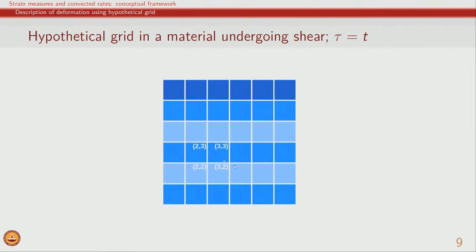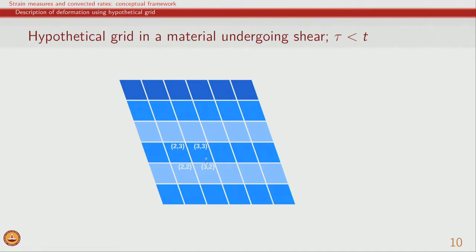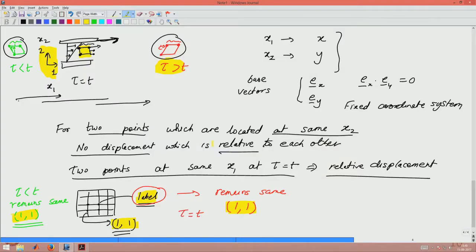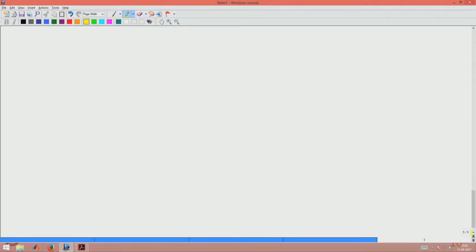and so therefore, these numbers that I have written here are in fact the convected coordinates, because the material particle is now labeled using these coordinates, and these coordinates are labels of a material particle. The material particle can change its position, but its label remains fixed, and since our coordinate is same as the label, the convected coordinates do not change. So, this is a unique way of following the material deformation, and this is somewhat counterintuitive to the cylindrical or rectangular or spherical coordinate systems that we usually use to solve engineering problems.